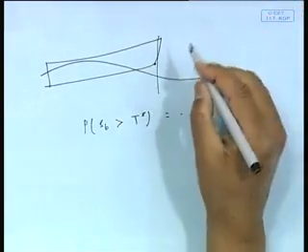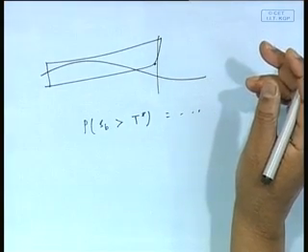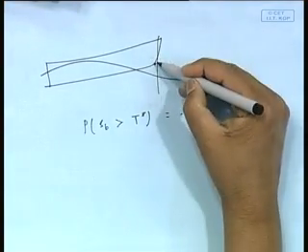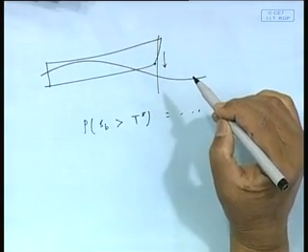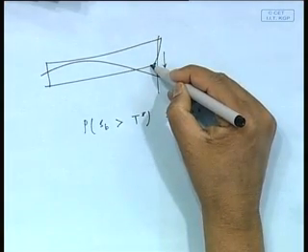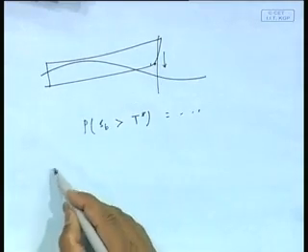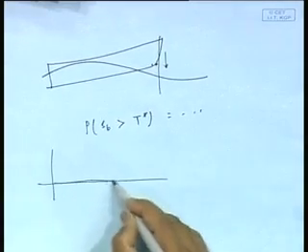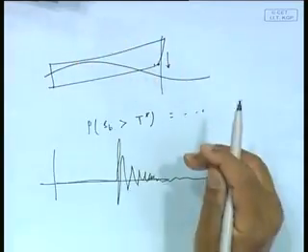The next question: what is slamming? It is very important for us to recognize this phenomenon of slamming. See, when this goes up, as it re-enters, it will give a very large impact here. And if you were to measure the forces here, you will find the pressure here will go like that, very large, like a bang, it is going to make a hit.